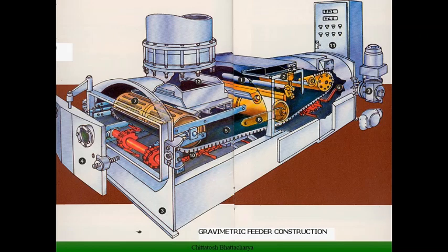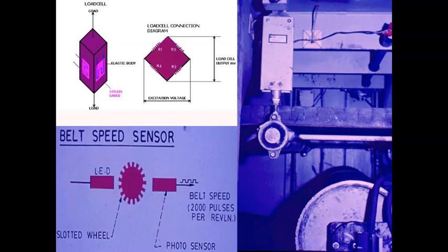There are load cells which are sensing the quantity of coal available on the belt per meter length, and there is a coal feeder intake piping which is providing the coal feeding into the coal feeder from the raw coal bunker, and beside that we have an AC motor which is driving the coal feeder, and there is a dyno drive arrangement that is varying the speed in meter per second, with which we control the flow of coal into the pulverizer.